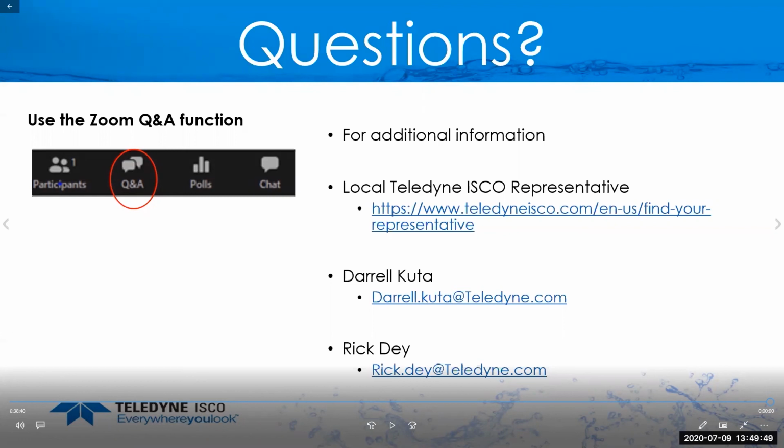Okay, here's a question. I know that non-contact is not affected by silt or debris on the bottom, but can it compensate for the flow area calculation? If not, wouldn't the flow quantity read higher than it is? Good question. The answer to that is both yeses. We are not necessarily affected by the silt level on the bottom, but they don't know that there's silt on the bottom. And yes, you can enter a silt level factor into the meter. Typically, all of them I would think would do that. And so it's going to take that out of the cross-sectional area. If you did not, you're absolutely correct. It would read higher than what's real.